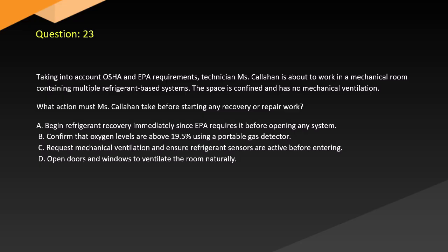A. Begin refrigerant recovery immediately since EPA requires it before opening any system. B. Confirm that oxygen levels are above 19.5% using a portable gas detector. C. Request mechanical ventilation and ensure refrigerant sensors are active before entering. D. Open doors and windows to ventilate the room naturally.